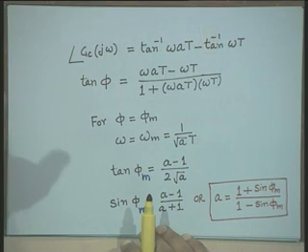But I just now told you very clearly that we would like to design the power system stabilizer in such a fashion that it may have some undercompensation, but it should not have overcompensation. The moment you have some degree of undercompensation, we get the advantage of an additional positive synchronizing torque coefficient, which is helpful. But we should not target to overcompensate, because the moment you overcompensate, it will produce a negative synchronizing torque coefficient.